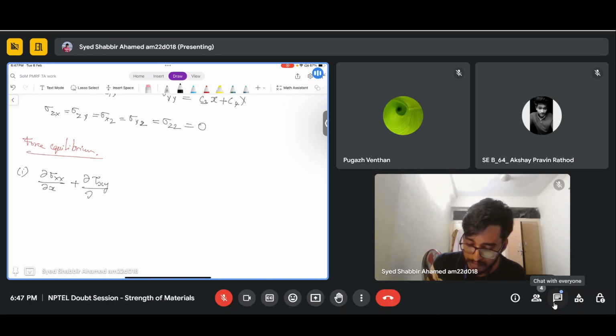So ∂τxy/∂y plus ∂τxz/∂z plus any body force. Let's say I'm writing it as bx, body force per unit volume.